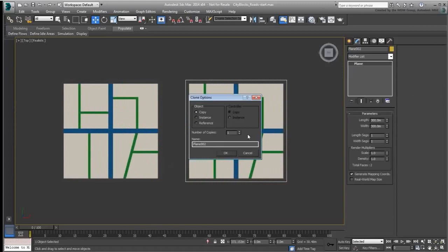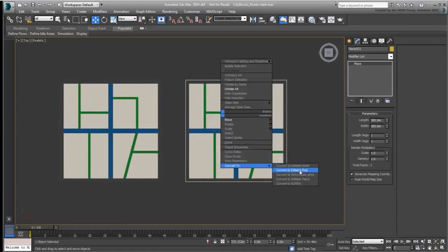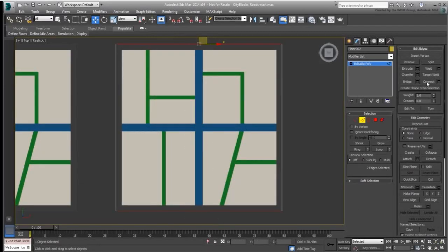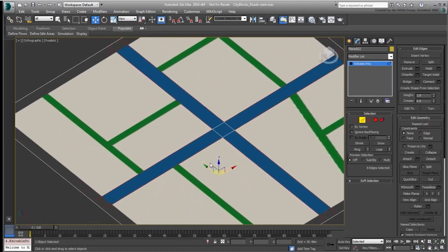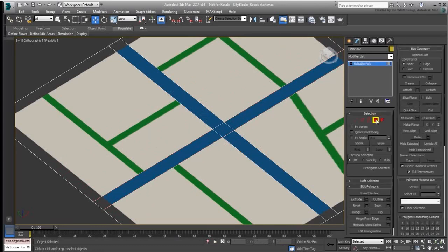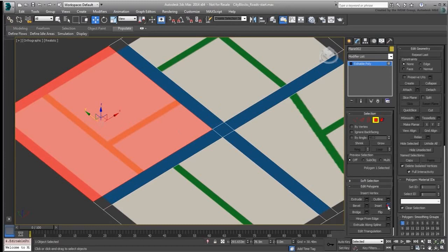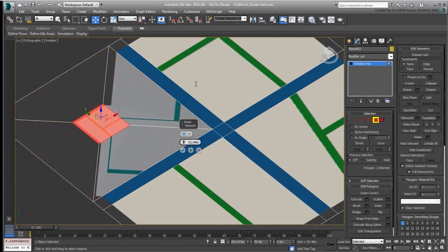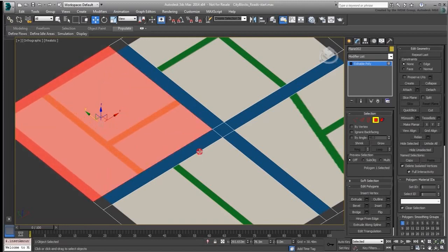If you elect to work with 3D geometry, as you have here, then one approach is to convert the object to an editable poly. You can then slice your way around the mesh using edit poly tools such as Edge Connect, chamfer, and poly insets. The difficulty in this approach is keeping the underlying texture in check. If you're not careful, moving sub-objects can distort the reference image. When working at a vertex or an edge level, you can prevent that from happening by using Preserve UVs. When working at a poly level, however, such as when insetting a face selection, this doesn't work well. There are ways around that. However, the workflow you will be using here bypasses that problem.